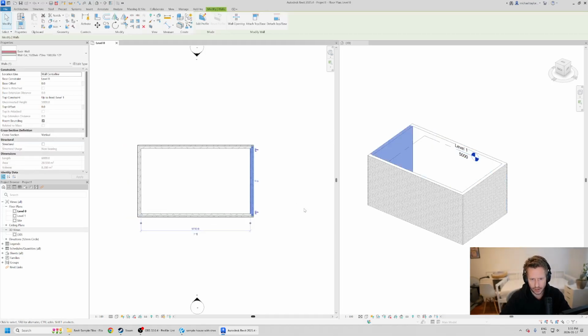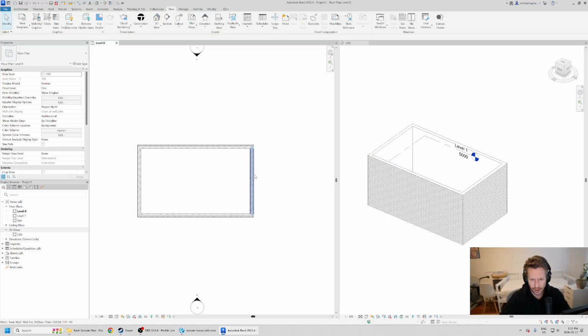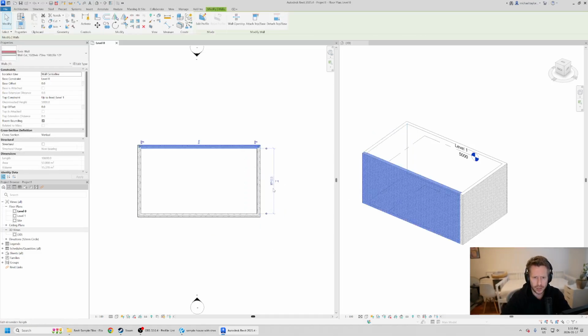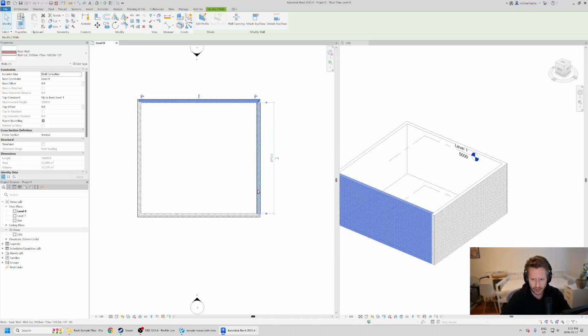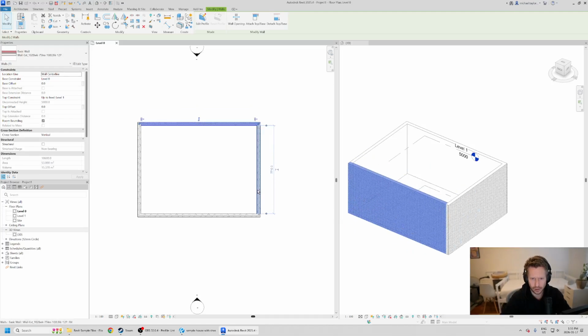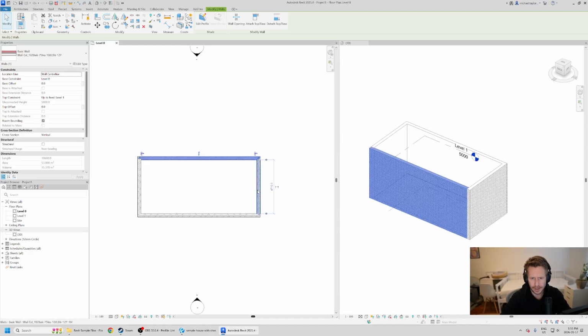So if I click on one of these, I can hover over and it's going to ask me, is this the wall you want? I'll click on it. And if I hit my little arrow key, I can shrink or make this wall bigger. You can see the temporary dimension there is changing, right? If I hold shift, I can make it bigger faster. I can't go up or down. It's going to let me go in the dimension of the original wall, perpendicular to the original dimension. So I can't go left or right. In this case, I can only go up and down.